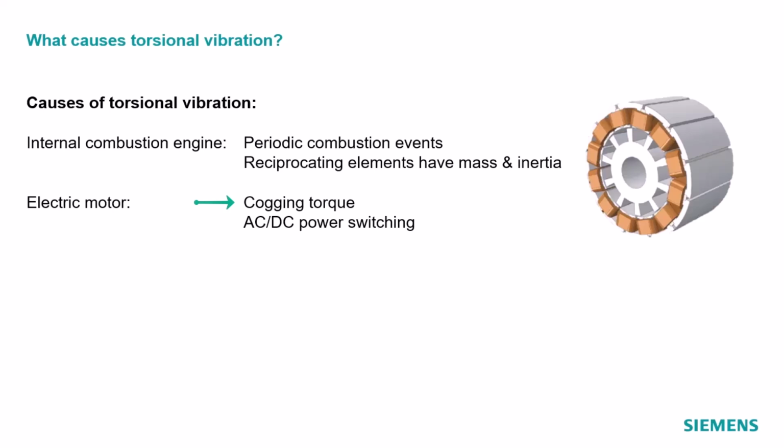With both this example and the combustion engine example, Charles, what would make it run smoother? If you had a lot of windings or just a few windings? A lot of cylinders or just a few cylinders? I say a lot of windings would make it run smoother with the electric motor. Yeah, because each one of these is a speed up, slow down. So you would have less time between speed ups and slow downs if you had 20 of these things versus 10 of these things.